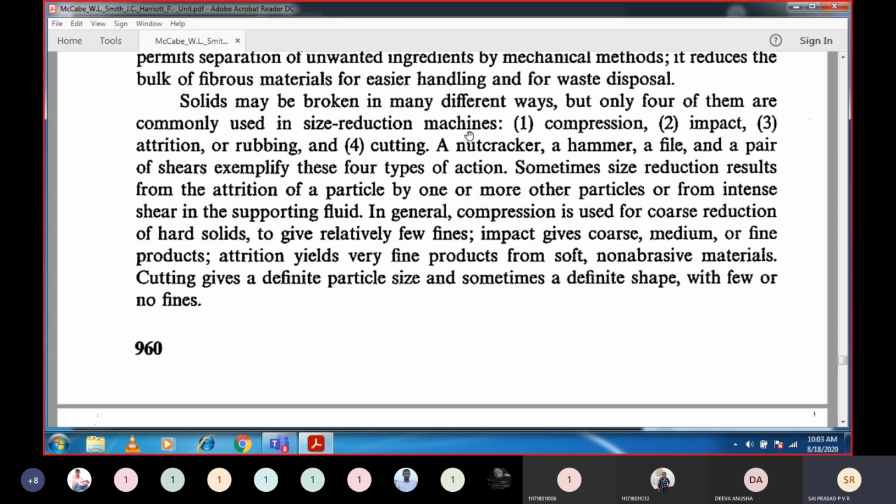The first step is what? We are supposed to immobilize the particle. Immobilizing the particle is called nipping in our chemical technology. If you nip a particle, you are firmly catching it and then applying the force on it. When you are doing some work on a bench vice, you tighten the screw so that the bench vice firmly fixes the material, and then you can work on it.